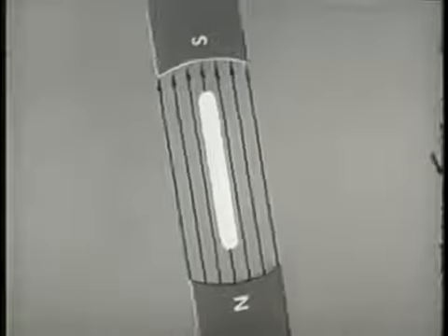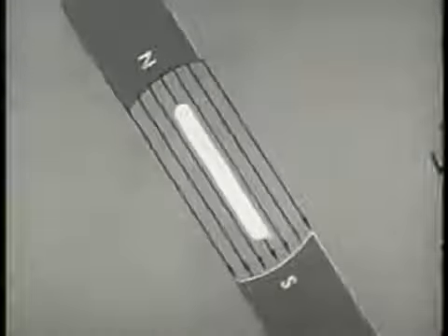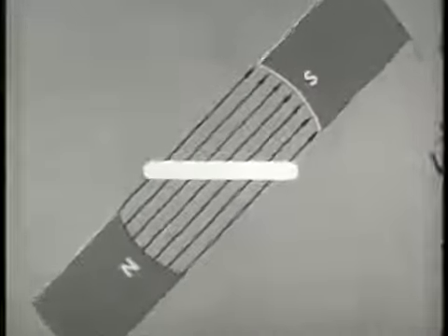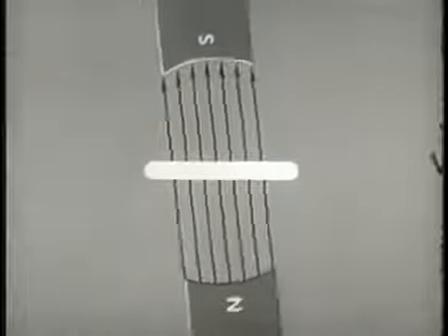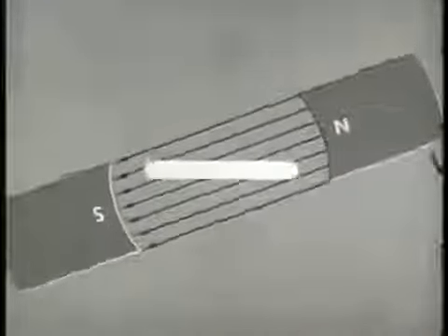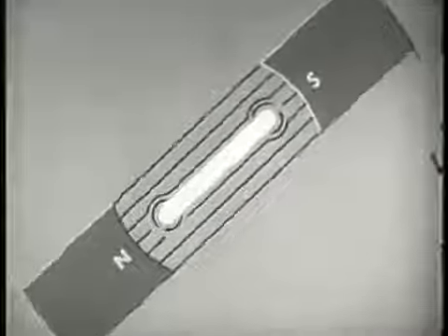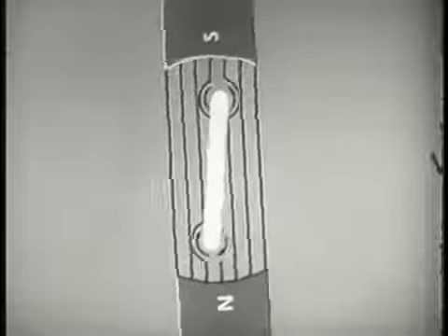If the speed of the rotor and the field were the same, there would be no induced EMF. No lines of force would be cut and no field built around the conductor. Obviously, there can be no motor action under those conditions. This, however, is an impossible situation. For if the rotor stops while the field continues to turn, relative motion will have been re-established. Lines of force are being cut once more. An EMF is generated and the resultant magnetic field will cause the rotor to move again.